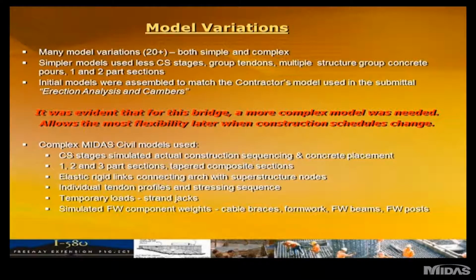So overall, I developed about 20 different models with some simple, as I mentioned, some complex. Again, varying the stages, the tendon groupings, going to individual tendons, breaking down the element pours of the superstructure and the arch rib to match what we were seeing in the field.